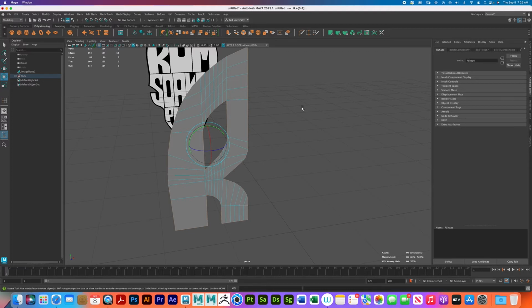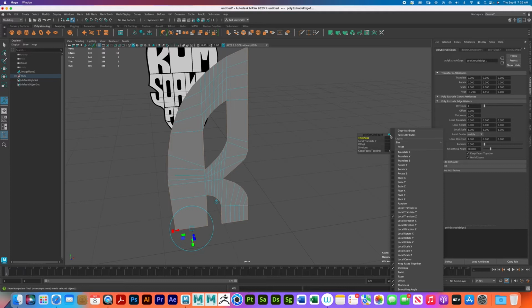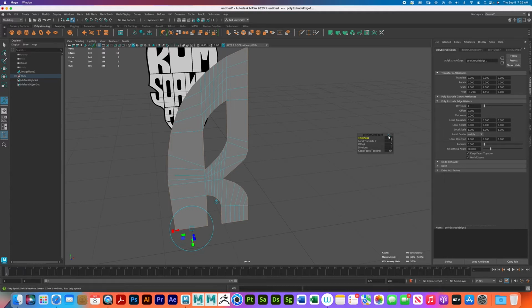So let's avoid that altogether and press Command E. And right here, I always tell people, if this is all the way here or more, it's going to do everything faster and it can crash your Maya. You want to click it towards the Pac-Man signal, and then you're going to slowly offset what you need. That's a supporting edge loop right there.